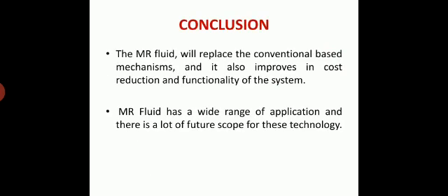So, conclusion. The MR fluid, whose viscosity is a function of applied magnetic field, will replace the conventional based mechanisms and it also improves cost reduction and functionality of the system. This MR fluid also has a wide range of applications. There is a lot of future scope for this technology. If these MR fluids are used in our day-to-day life, it will provide a greater solution to many maintenance problems because these fluids are resistant to water and dust contamination. And even the temperature variation doesn't affect the fluid's performance up to certain limits.